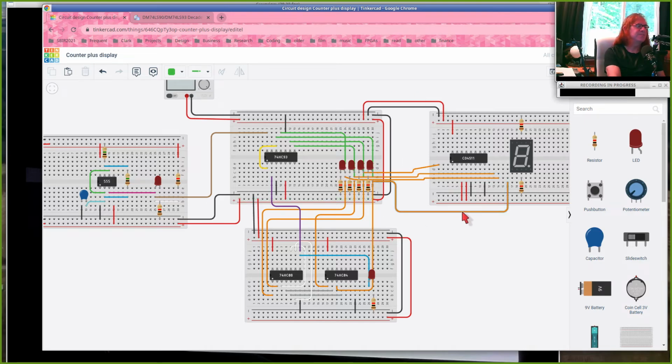so that you can successfully build it. I usually prefer to work on just a few big boards, but I knew there was a problem here, so first I just built the counter and I drove it with a function generator, and then I put the 555 on a separate board, and then I added the reset circuit, and so it just kind of logically broke out this way for me.